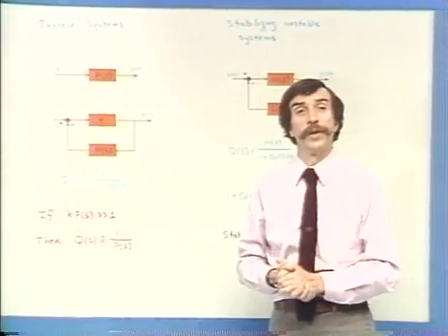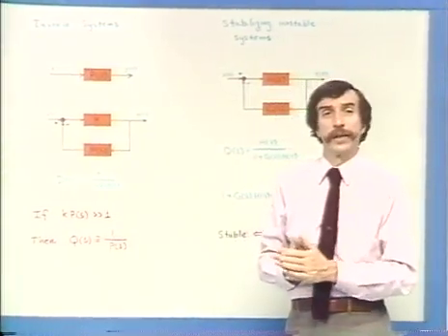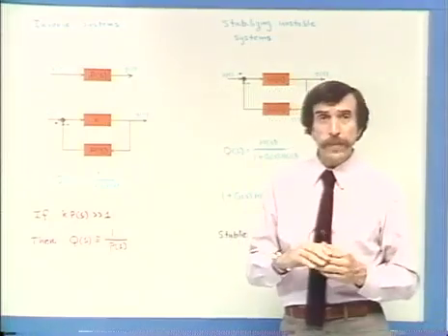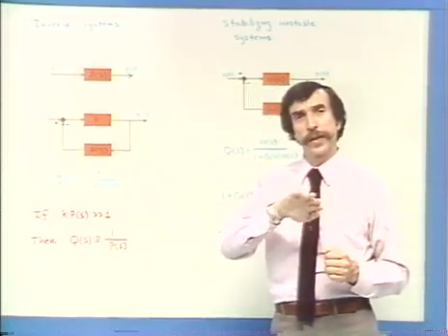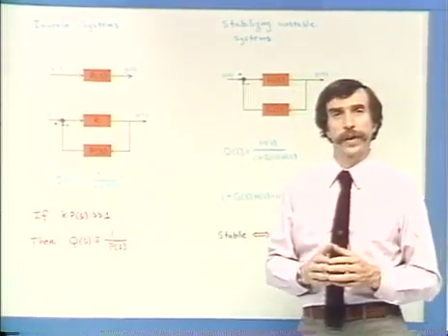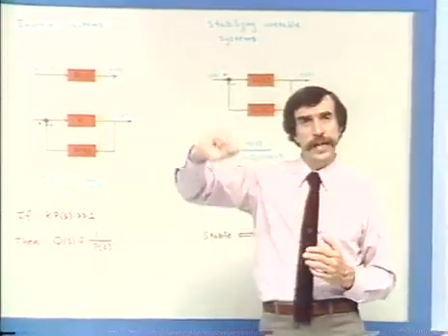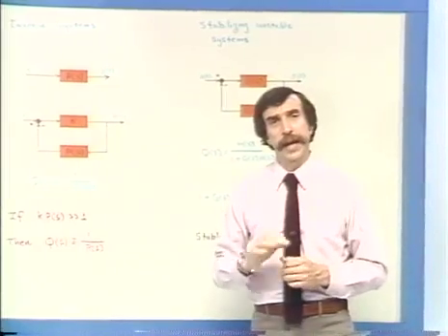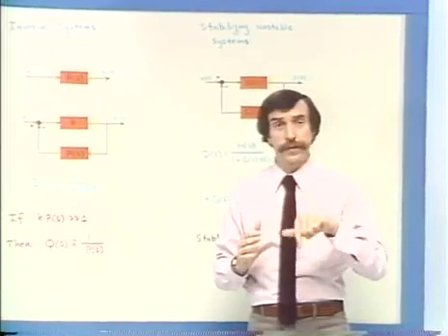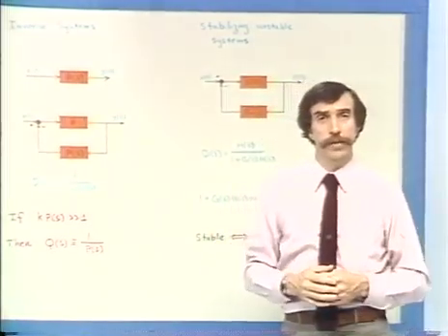And a system of this type is used in a whole variety of contexts. One very common one is in building what are called logarithmic devices or logarithmic amplifiers, ones in which the input-output characteristic is logarithmic. It's common to do that with a diode that has an exponential characteristic, and using that as feedback around a high-gain operational amplifier.